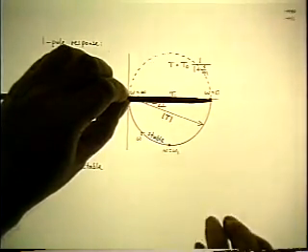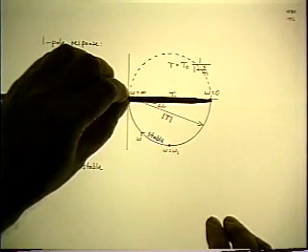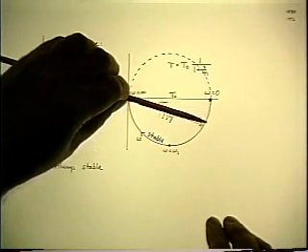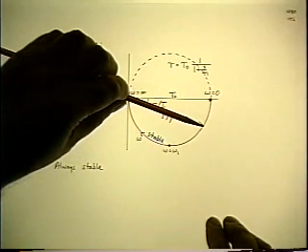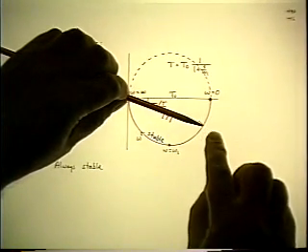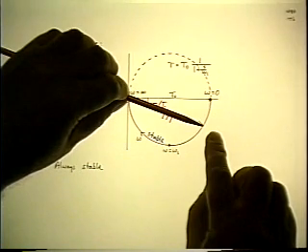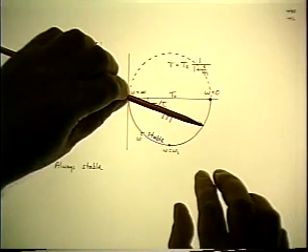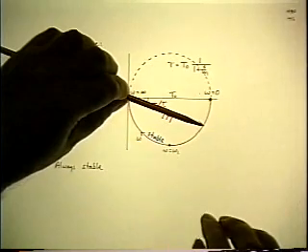Then you take a higher frequency and find the magnitude of t, which is now a little less than t0, and it starts to build up a lagging phase angle. So you mark the end of that one with some arbitrary value of frequency. The first one of any particular interest is the corner frequency itself.